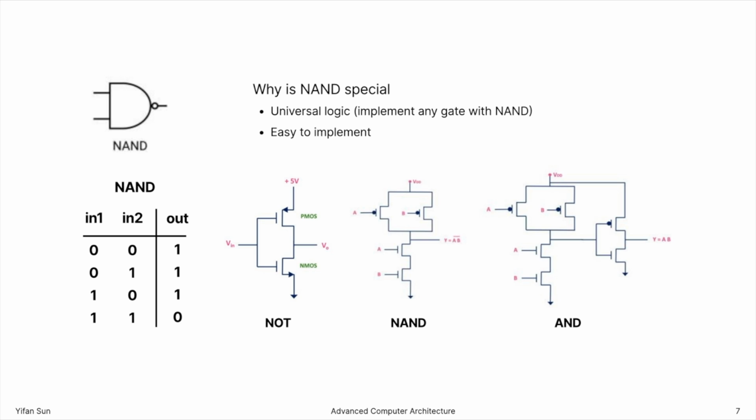And if we consider other types of gates, in fact an AND gate is composed of a NAND gate and another NAND gate. So there's really no NOT gate in the circuit. There's only NAND and another NAND, just combined in a different way. So a NAND gate requires 4 transistors. Just be slightly aware of how many transistors are required if we want to implement something.